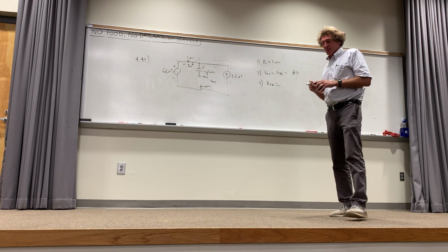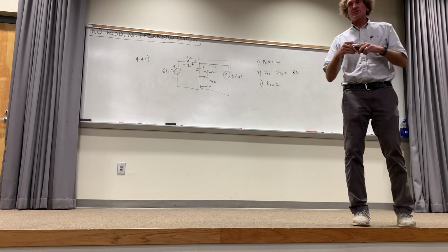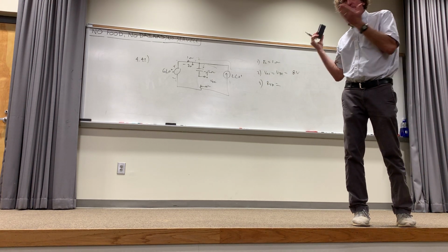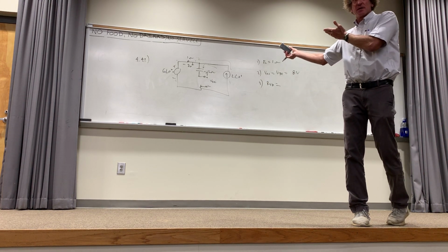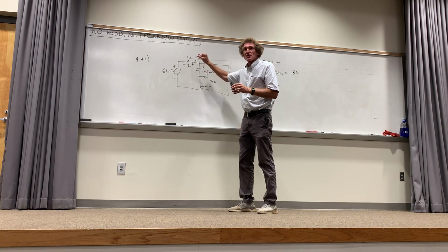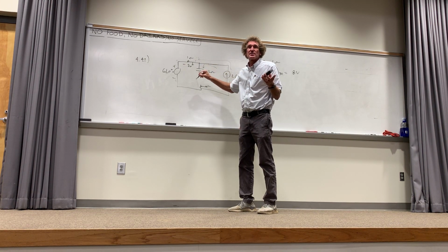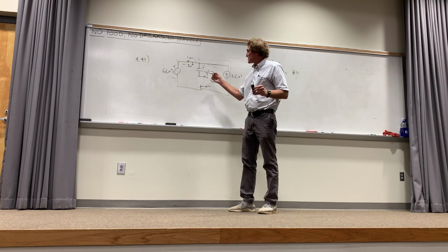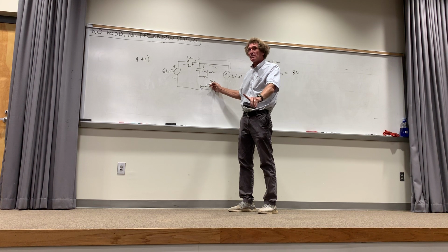But do you treat the resistors differently for the different methods? You're trying to say, is there something different about mesh analysis compared to this? Yes, there is, and here's why. In mesh analysis, you would take the sum of the voltage drops around a closed loop equal to 0. In fact, I'm doing that, but I'm not stating that because this voltage drop I break out entirely by itself.